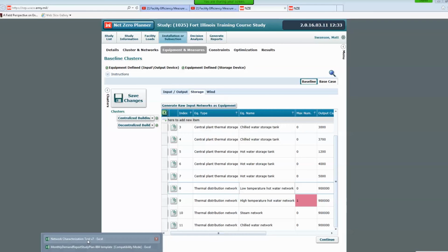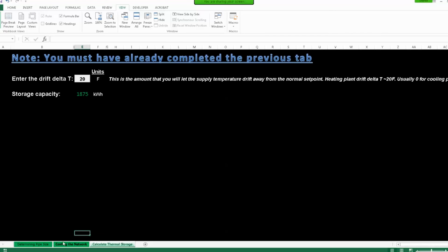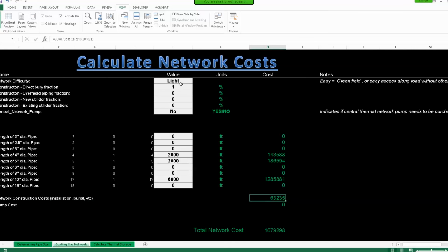So I realize this is going to be unfamiliar. Going back to this spreadsheet for a minute, there are different construction methods here, and so you'd have to break it down. Most installations choose to do direct bury, where, as it sounds, they would directly bury the pipe in the ground right there. But you've also got these other options that are itemized out below, and you just write them up as fractions. At this planning level, if it's 80%, you could just put 0.8 in here, and then 0.2 someplace else. You're just dividing this up as fractions.